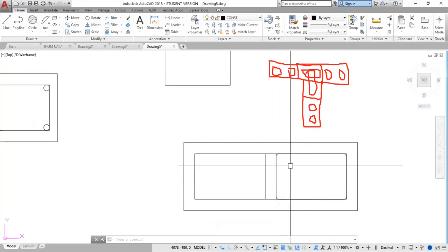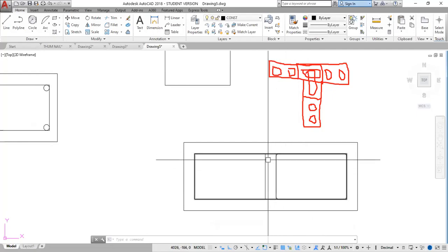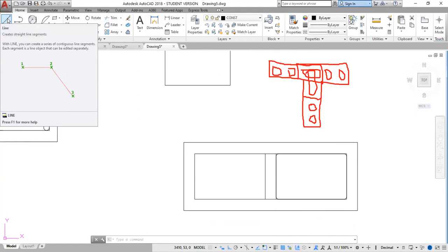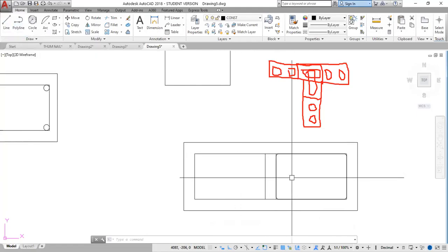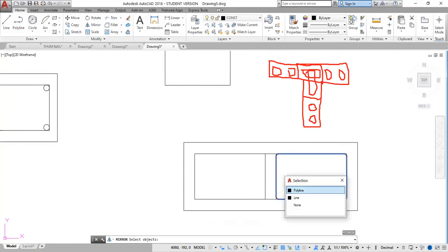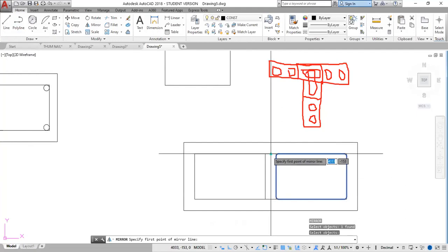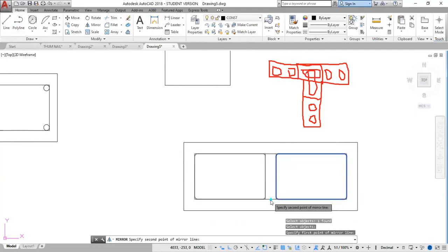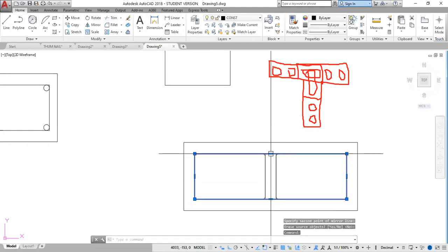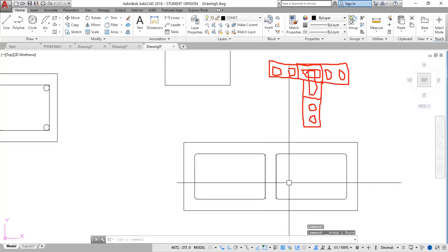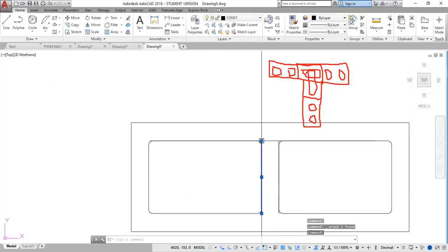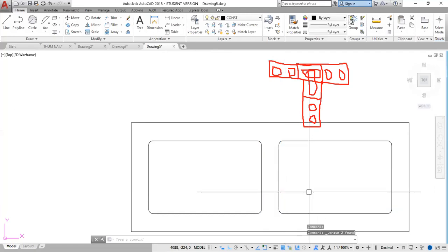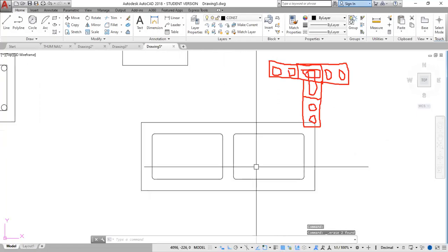So I'm going to copy this. I'm going to draw a line here first, or mirror this side first. Mirror, MI, enter. Click this polyline, enter. Select mirror line here, mirror point here, and here, enter. Now I'm going to delete this. Now I have my block with those lines there. Delete those lines. So I now have my block with that nice little edge.